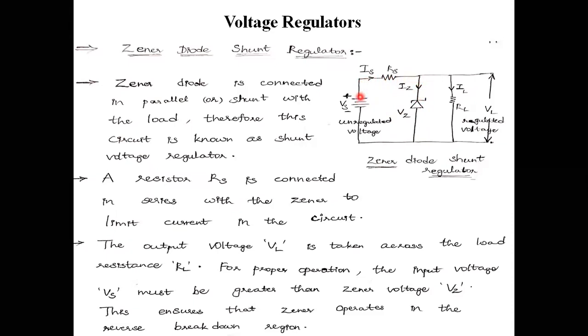Cathode terminal is connected to positive and anode terminal is connected to negative. That is the meaning here. Why is the circuit arrangement like this? In order to make the voltage constant here, to regulate the voltage, I am connecting the Zener diode in reverse fashion here. Okay, this source voltage Vs is connected to some limiting resistor, a current limiting resistor. This is Rs.